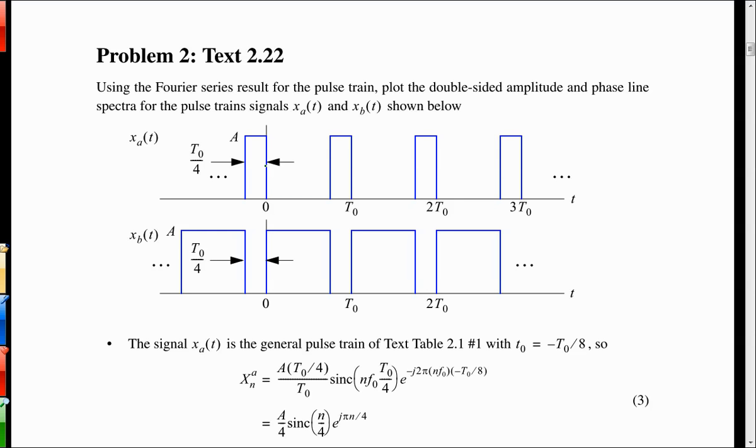You could actually just invert the top waveform, in other words, flip it down like that, and then add a constant to it to raise it up, and you would have the waveform. Can you see how that would work? Adding a constant to a waveform, level shifting like that, doesn't do anything except change the x0 coefficient. Flipping the sign would change the angle by 180 degrees.